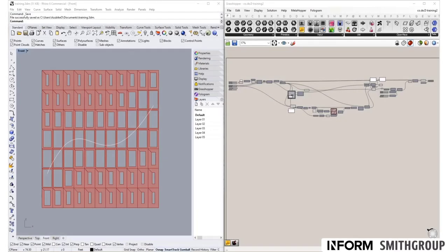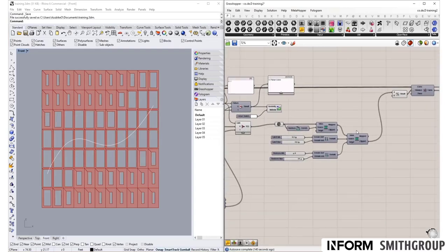To wrap up volume 1, we're going to use the panel frames from the attractor exercise to create panel frame types, visualize those panel frame types using color mapping, and create new panel frame systems to include solid panels. To get started, from the remap operation,